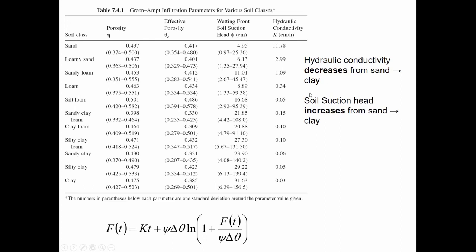So the soil suction head goes the opposite of hydraulic conductivity. It increases in the direction of sand to clay. So the clays have more suction. So the driving force is going to be the difference between the soil suction and the penetration depth, L.